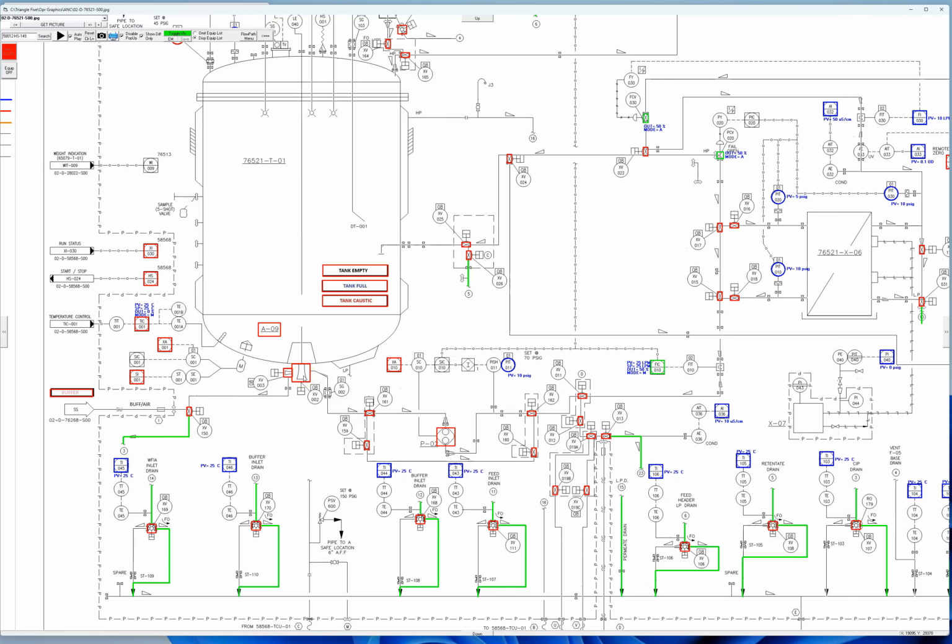If you select this, it highlights it. When it's highlighted green, that means previously it was red, which is not running, and now green. And right now you just go through all that, and you show your previous state to current state. Right now this is one valve at a time, but if you change several at the same time, especially like EMs, it'll show you what all valves were different from one flow path to the other. So that could be useful to decipher the differences between flow paths.